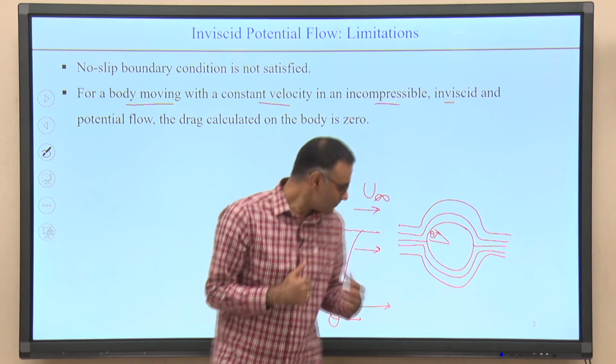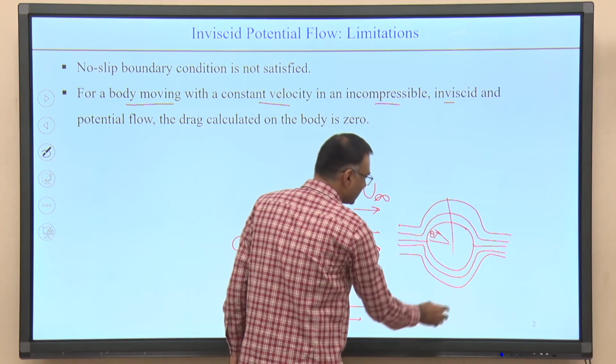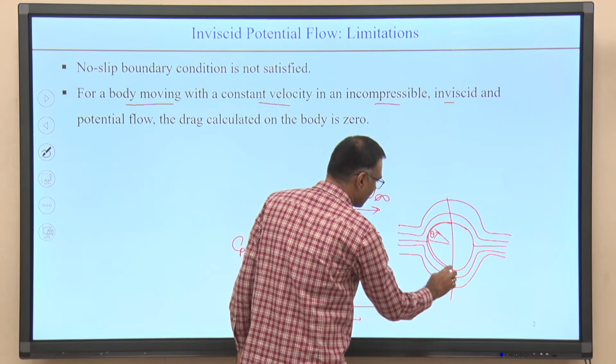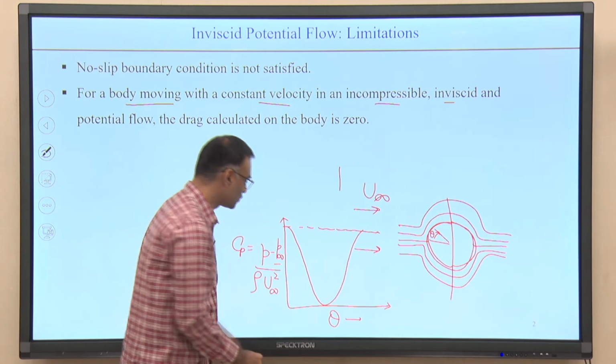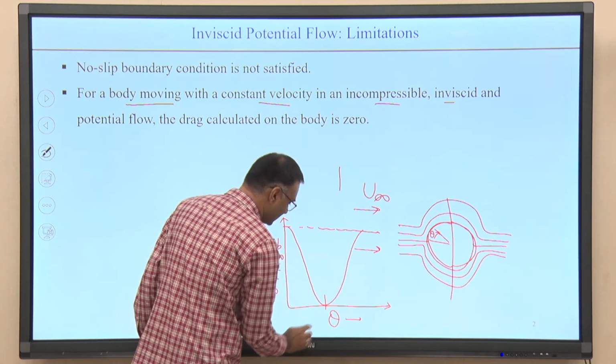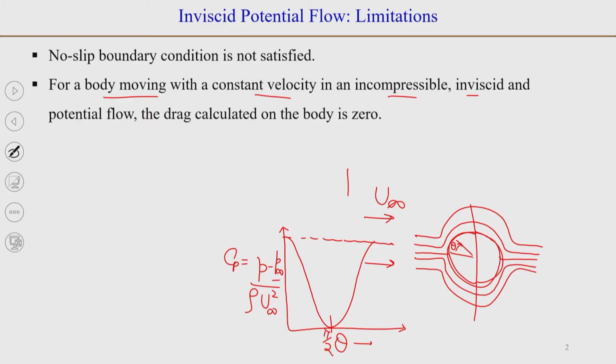Now, as we can see here, the pressure on the two sides of the sphere, on this side and that side, is same. So, this is basically the angle pi by 2, where the Cp value is minimum, and then angle pi. So, the pressure has been plotted on either half, you can say top half or bottom half in this image.